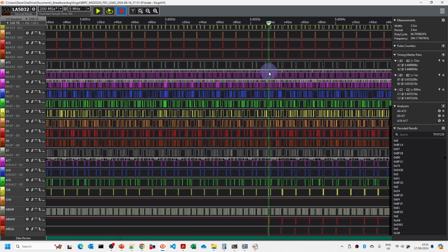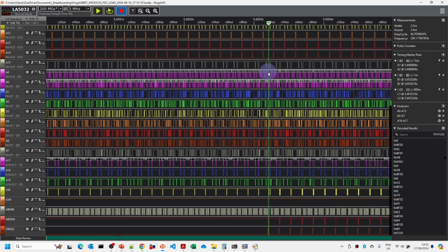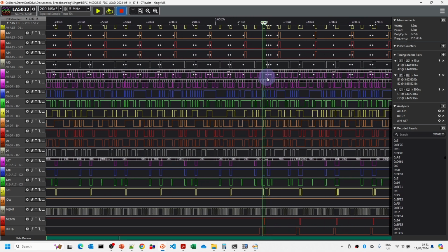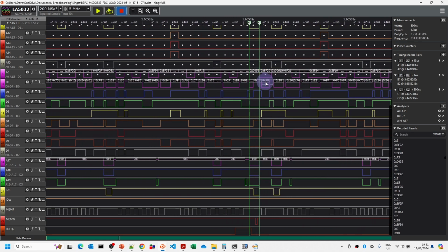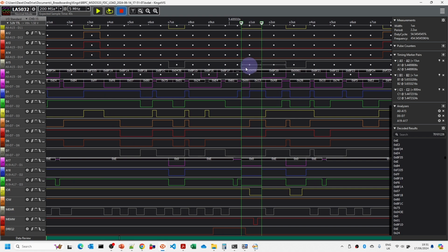So I'm not going to do any further work in the video at this point in time, but the Diagnostics ROM has helped to highlight where there are some potential problems reading and writing to the DMA controller. We've also been able to see that we get these values being reversed. So what I think I'll do is take one of the DMA controller tests that I had running standalone and add it into the Diagnostic ROM.